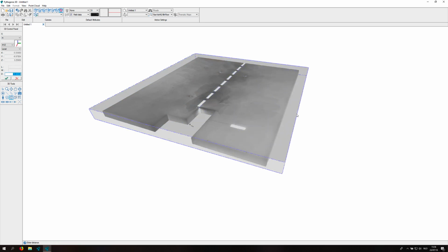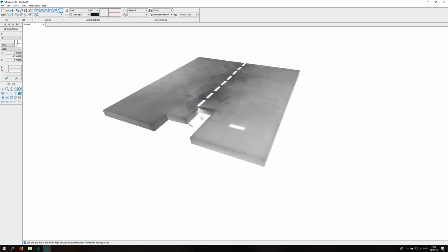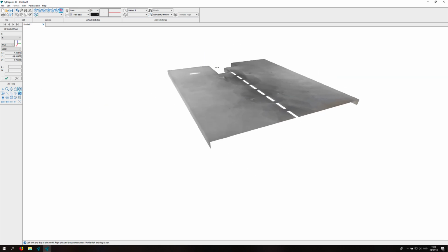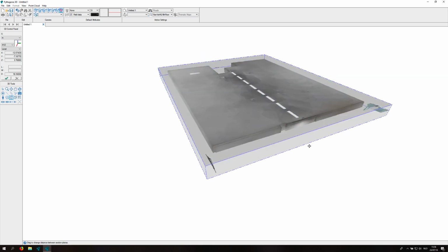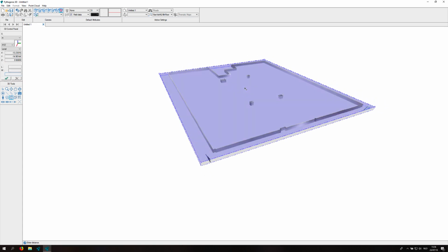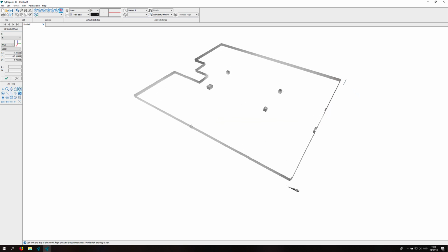In this case, we produce a slice of the upper part of the room. Why? Because then we have all the walls. If you want to have the windows in the slice, then you can move the slice up and down to see those windows and doors in the slice. So now the slice is ready to be vectorized.